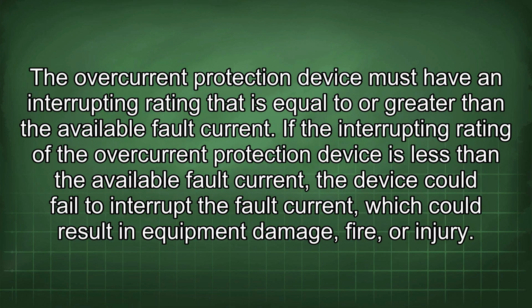circuit. The overcurrent protection device must have an interrupting rating that is equal to or greater than the available fault current. If the interrupting rating of the overcurrent protection device is less than the available fault current, the device could fail to interrupt the fault current, which could result in equipment damage, fire, or injury.